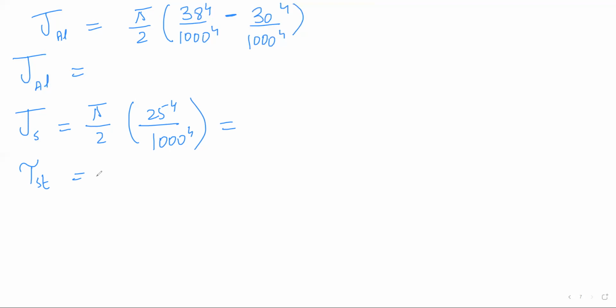Did you find the value of T steel? Give me the value of torque of steel. It will be 120. So find the torque of steel, then using that torque of steel, substitute that, very good, and then find the torque of aluminium using that TS. After that, we will put in the aluminum part and double check whether it's exceeding the allowable.